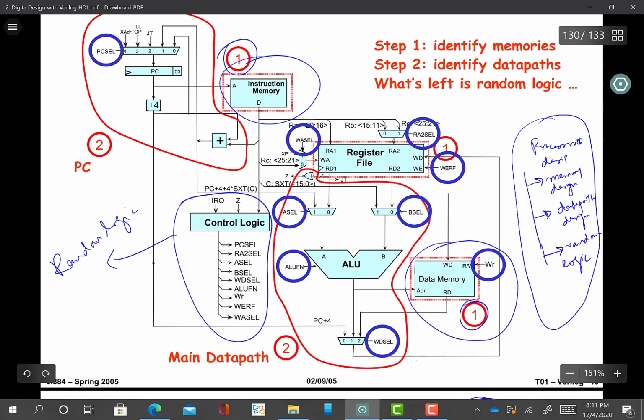Again, if we talk about mapping it to ASIC, or mapping it to FPGA, there are different methodologies to do it. For example, with FPGAs, we already discussed that we should map memories to block RAM. We should not map them to flip-flops because they are so expensive. Similarly, for ASICs, there are different kinds of memory cells for memory design. So we should consider a specific technology for the design of memories compared to data path logic.